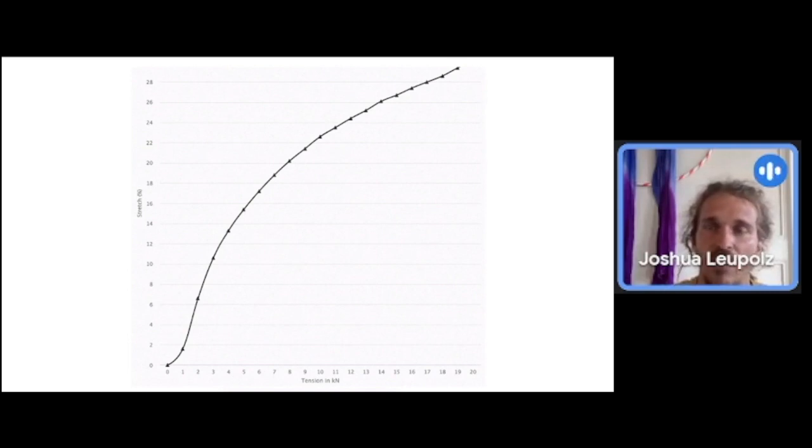Even a lot of manufacturers say themselves that you cannot really compare webbings with each other using these stretch values. You get a rough indication. If a webbing has 18% stretch, it most likely feels more bouncy than a webbing which has 10% stretch. But in the end, if one manufacturer says 16 and the other 18, you really need to feel the webbing to see what's going on. But as an engineer, my approach is that we should somehow measure it, because if you can feel on the line that it feels different, you certainly can measure it. You just need some creativity to figure it out.